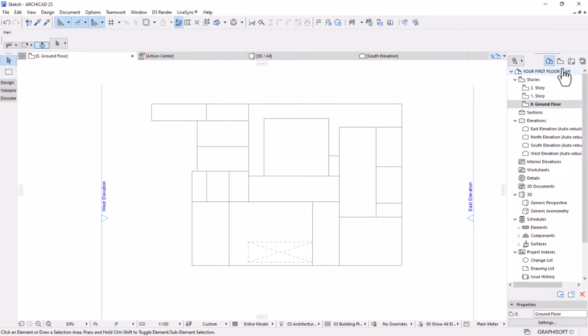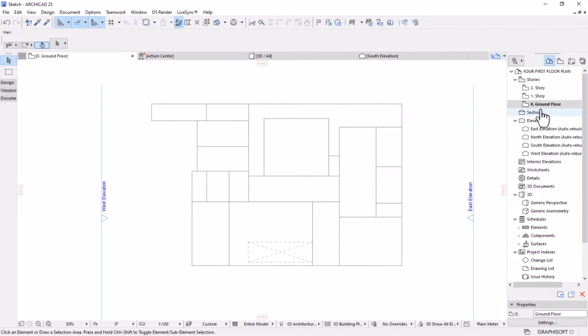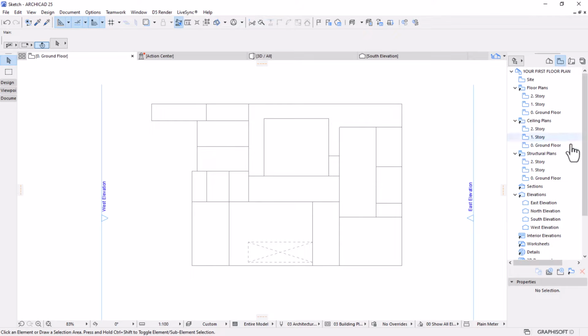So another section within the project browser is the view map. The view map is more or less the same as the project map, but the difference here is it doesn't capture, it's you, the user, who is going to store the information about your project. So instead of capturing the floor plans, you are the one supposed to come and store and customize these views or viewpoints. So the difference is that here you can customize and have different parameters on your view.